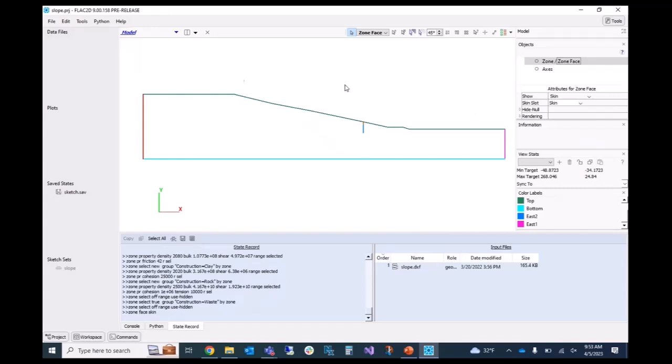You can, of course, just use coordinates when you're applying the boundary conditions. And in a lot of the simple models you've been doing so far, that works fine because everything is at x equals 0. But when you're doing real life models like this, often they're in some sort of mining coordinates or something. So it's not at x equals 0. It's at x equals minus 127.3. So using those coordinates is kind of a pain. It's easier just to say, give me the west side.